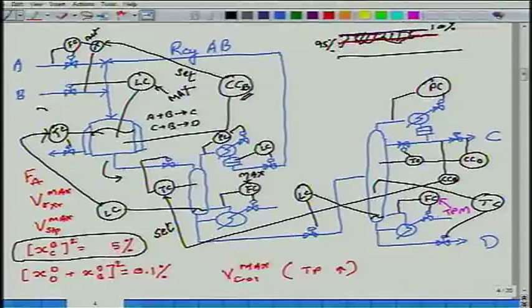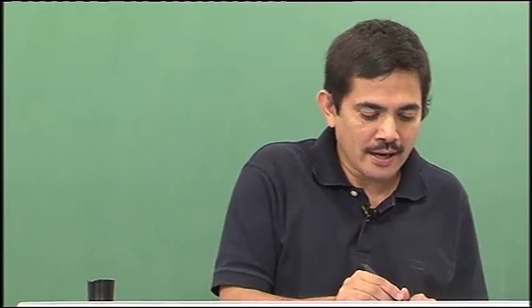I adjust the throughput manipulator, and by adjusting it, I essentially adjust how much fresh A and fresh B are getting sucked in. We argued how that gets done. This level goes down, that sucks in more from the previous unit; that level goes down, that sucks in more from the previous unit, until more or less A, as is necessary, or fresh B gets sucked in. Yes or no? Right? So I can always adjust this throughput manipulator to get whatever FA I want.